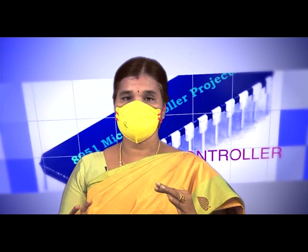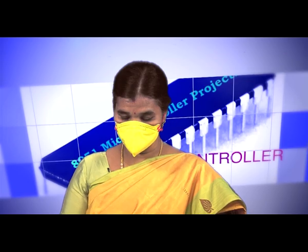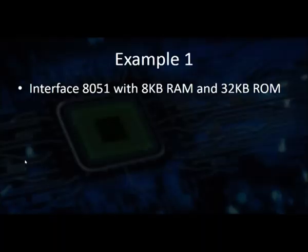So, based on this concept, now we will discuss some examples. Example 1: interface the 8051 with 8 kilobytes of RAM and 32 kilobytes of ROM. Here I have been given 8 kilobytes of RAM. What does 8 kilobytes of RAM represent? From this I have to understand how many address lines are required.